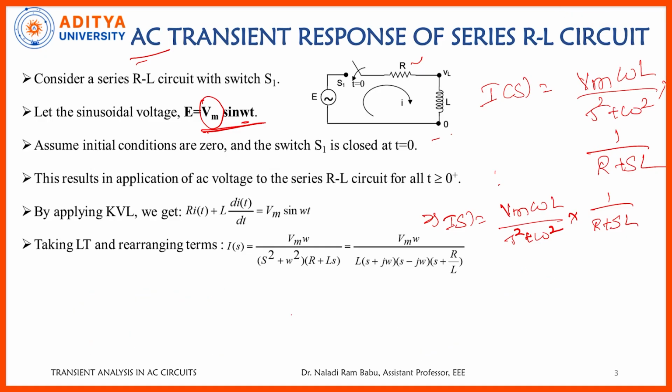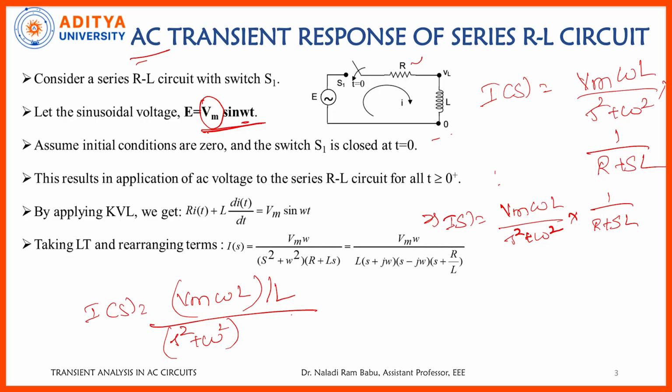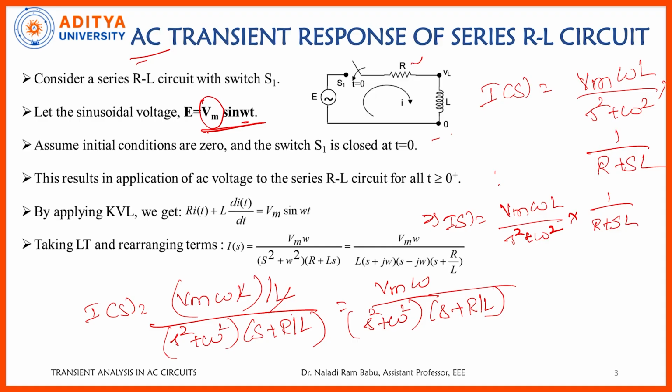Now I of s is equal to Vm into omega L whole divided by L, because I am taking this L outside, and it will be s square plus omega square into s plus R by L. Here the L gets cancelled, so it will be Vm into omega by s square plus omega square and s plus R by L. Now I want to solve this equation in terms of I of t.